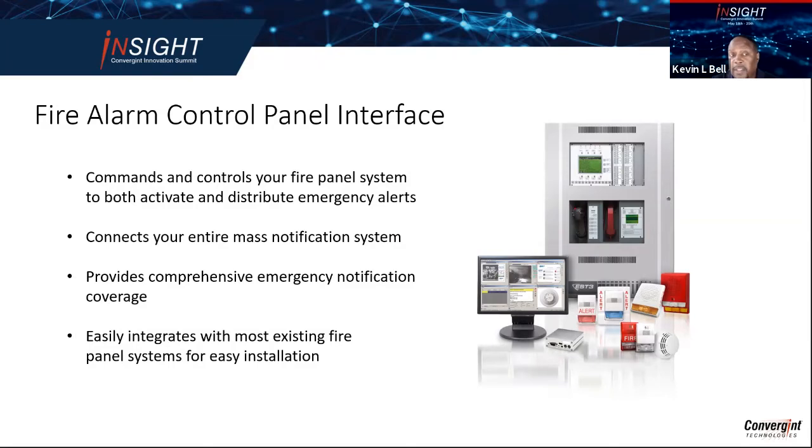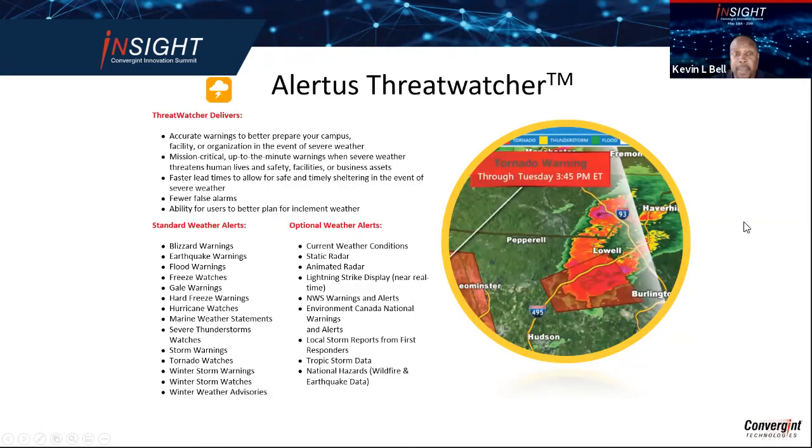If you are planning to upgrade your fire alarm system in a building, I would recommend that instead of putting in a horn strobe system, you put a voice evacuation fire alarm system in there. The only difference is instead of a horn strobe, you're using a speaker strobe. Instead of a cable with 2 conductors, you have them pull a cable with 4 conductors. There's no difference in labor. The labor is the same, but what you're getting is mass notification throughout your facility, and you really didn't spend that much more money, just an audio source unit instead of a horn strobe unit. So that's what I would recommend.